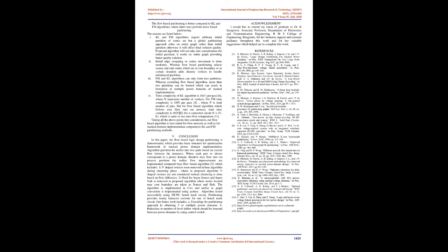The proposed algorithm does not take the initial partition into consideration; it works on the entire graph, providing a better quality solution. 2. Initial edge swapping or vertex movement is done randomly, whereas flow-based partitioning selects source and sink nodes which are at the core boundary or, in certain situations, adds dummy vertices to handle unbalanced partition.